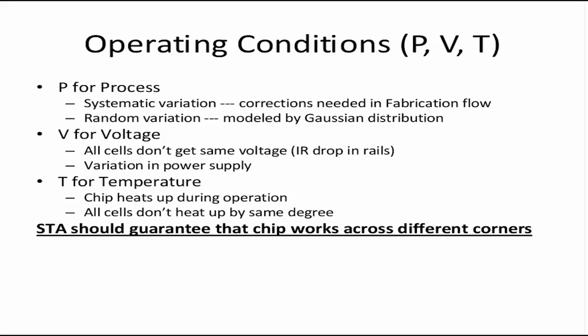That means these variations affect either all the wafers in a similar fashion or all the dies on the same wafer in a similar fashion. So for example, let's say you are targeting a 65 nanometer process. Now let's say the whole fabrication process by a particular fabrication lab is not optimized, and there is some error in their formula or in the manufacturing process, which will result in all devices having a fabrication value greater than 65 nanometers. This is called a systematic variation.